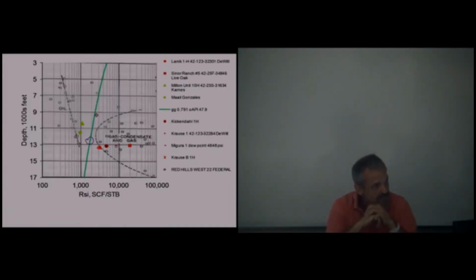One way to classify or identify the reservoirs, whether retrograde condensate or dry gas or oil, is just by applying the phase diagram. We can classify what kind of reservoir it is. But can we figure out the type of the reservoir physically, by taking a sample from the separator or from the wellhead? If it's producing only gas, we can say this is a dry gas.